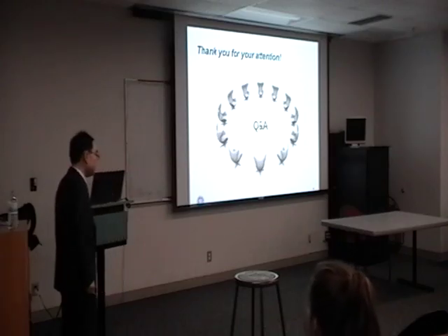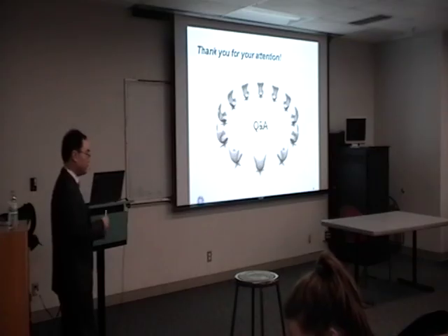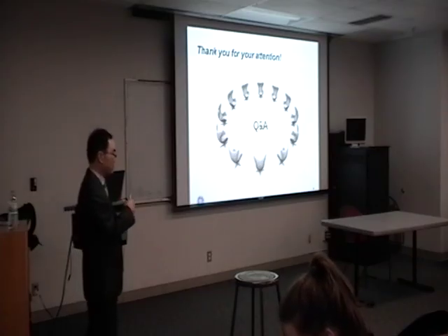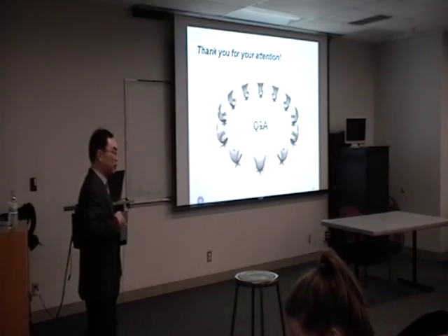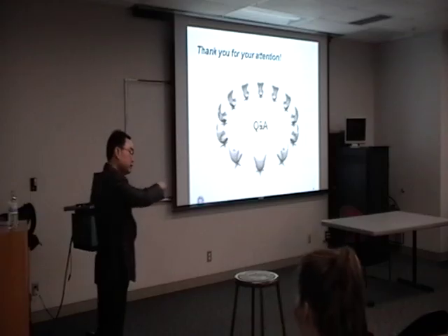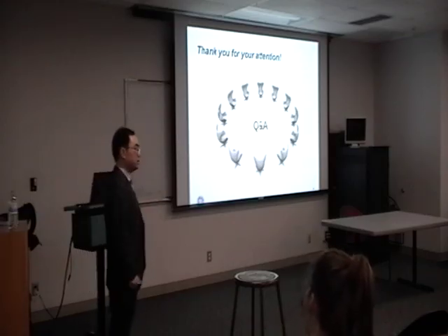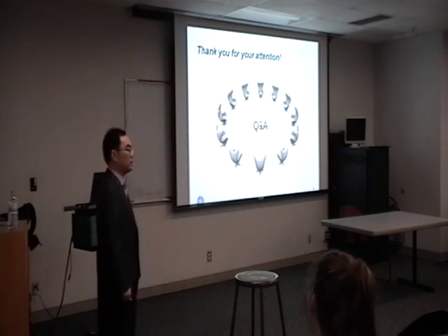Okay. The simple answer is that it changes the scattering effect. The more difficult answer is that we change the correlation of the turbulence in the spanwise direction. The serrations break down that correlation, which changes the scattering effect.